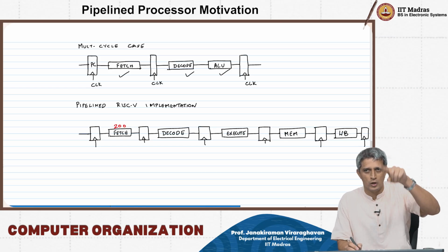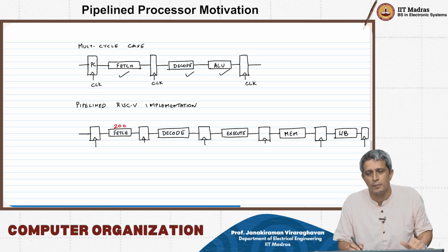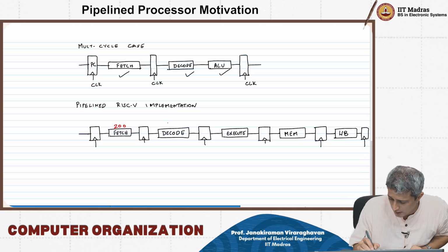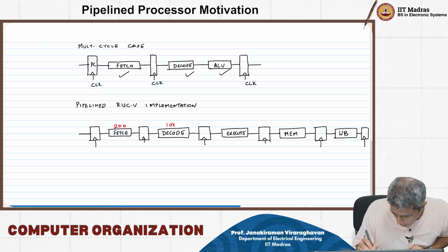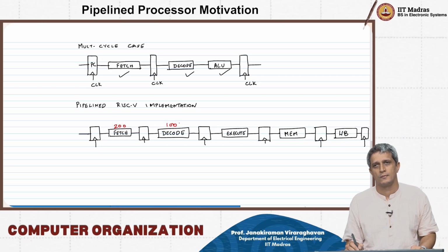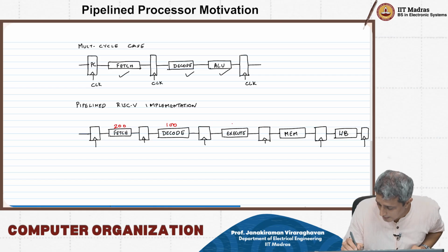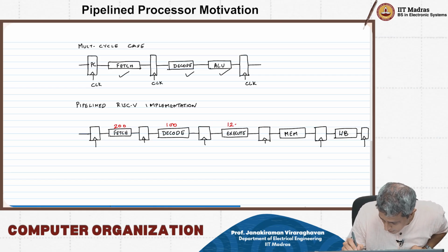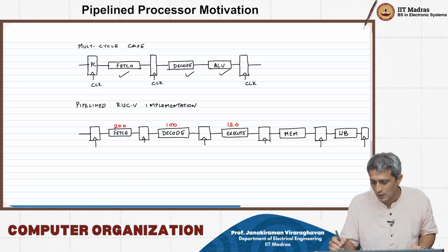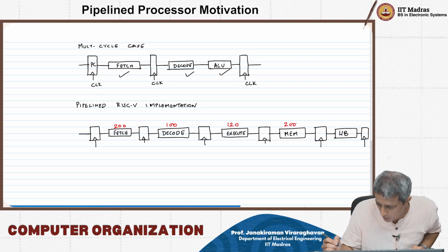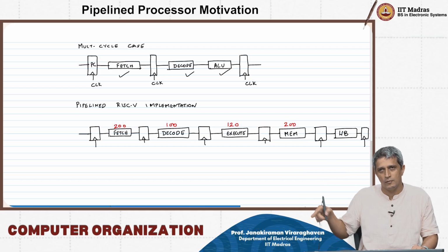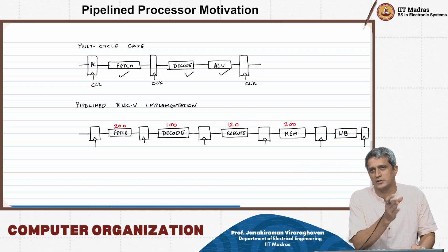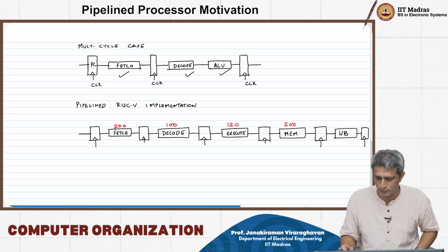You remember that whole critical path we spoke about, so typically this was limited by the RF read part, and that was about 100 picoseconds, the register file read time. And then the execute was just the ALU delay, which is 120. Then memory was back to 200, and the write back is basically just the feedback part, some multiplexer plus this register file delay.